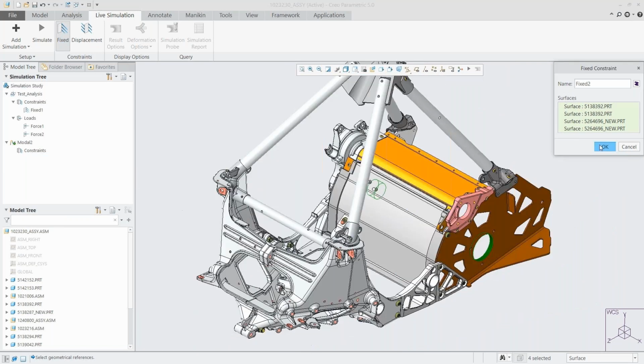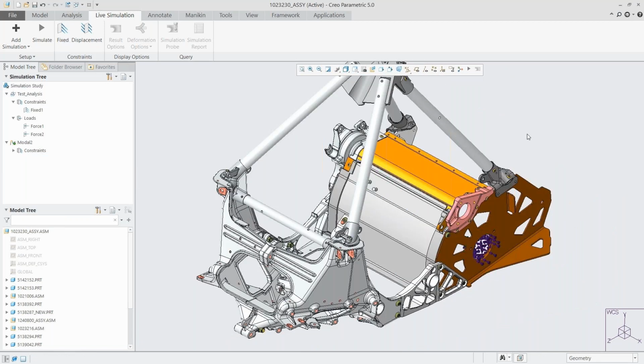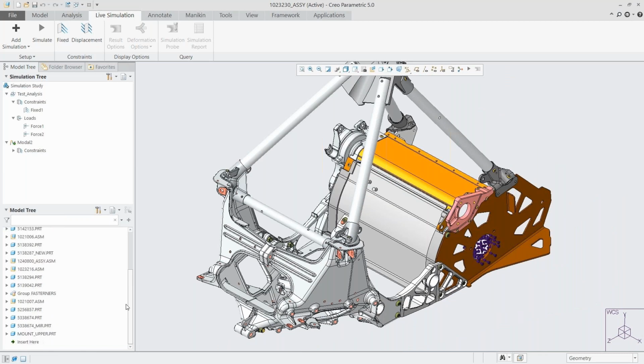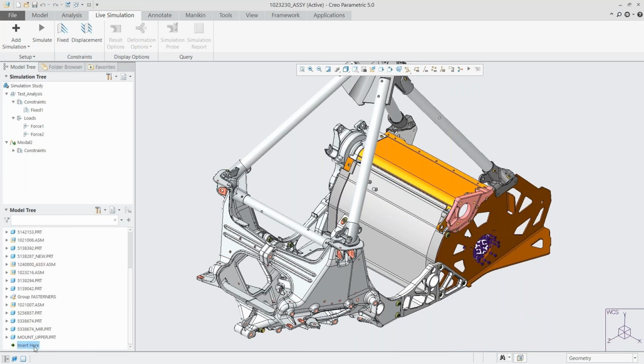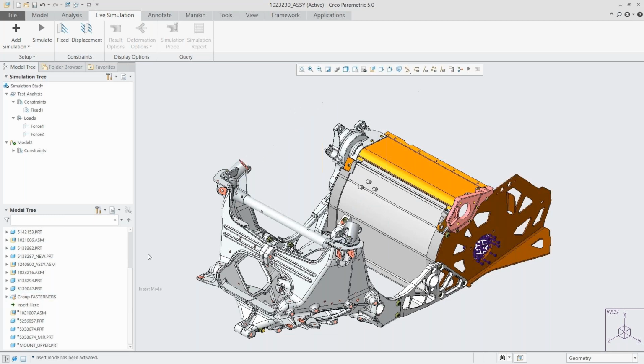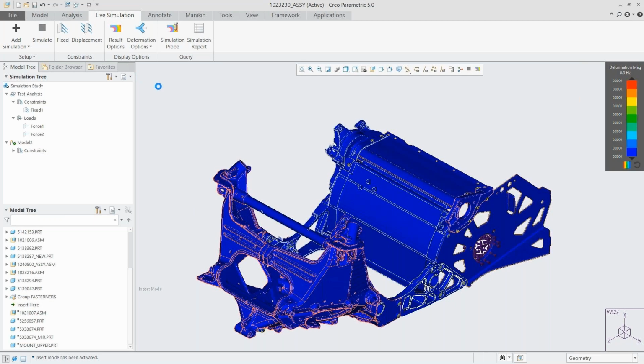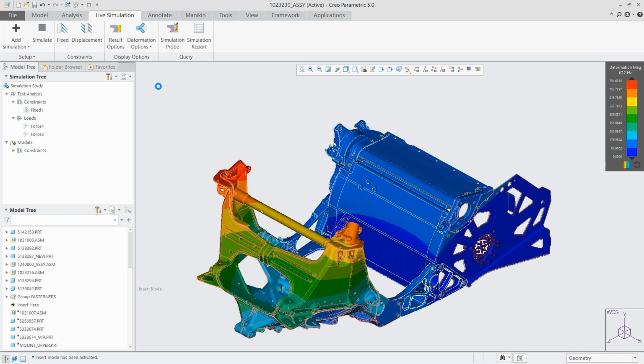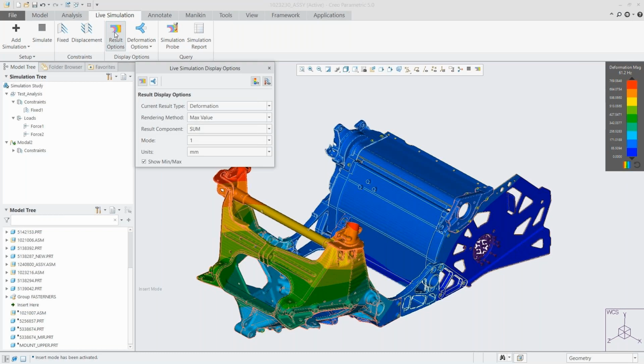Now that we have this laid out, let's go through and simulate this. I want to focus maybe more in on just the chassis. So let's get rid of that support structure that we added in, and then maybe we could add that back in later. All right, so we can see here now, as soon as we click that analysis, the vibration is being looked at here. Maybe we're looking at a certain mode here where we're getting about 60 hertz, and that's our frequency mode, and that's the part that we want to study. So we can see how maybe that's going to be affecting our chassis here.